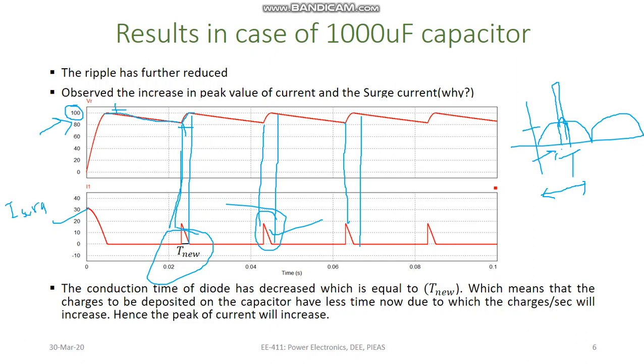Even if you have considered all these values, the surge value of the current is very large compared to the RMS value or the average value of the circuit. So it is necessary that you take this factor into consideration as well, and whenever designing, make sure that your diode does not get damaged from this very first surge that will come.